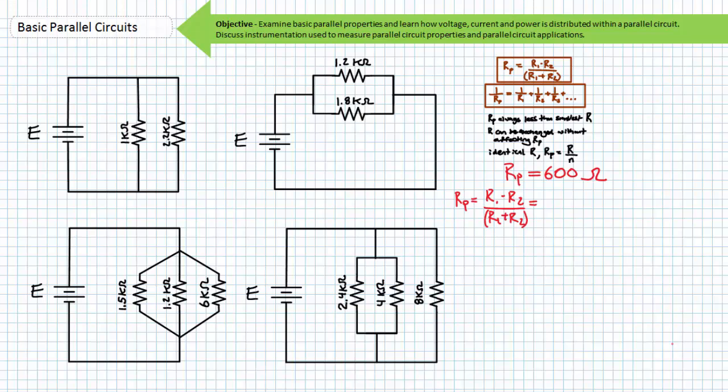I'll take a brief foray into the mathematics surrounding this calculation to point out three properties. Number one, the order of resistors in a parallel relationship can be exchanged without affecting the final outcome. Number two, identical resistors in a parallel relationship can be simplified using a shortcut. And finally, three, one can use the two-resistor formula to calculate total resistance of a parallel combination consisting of more than two resistors and gain intermediary results. Using the two-resistor formula on this circuit and the fact that order of engagement does not affect the outcome allows us three different paths to reach this same goal.